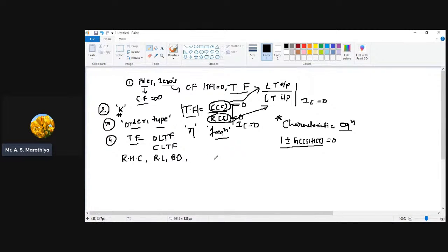for any physical system. So the mathematical expression of the transfer function for any physical system is finally in the form of K, where K is nothing but the overall gain of the system. Then we have a numerator polynomial of order n, and a denominator polynomial of order m. That means we have s to the power n, and s to the power m. And finally we comment on the relationship between m and n.